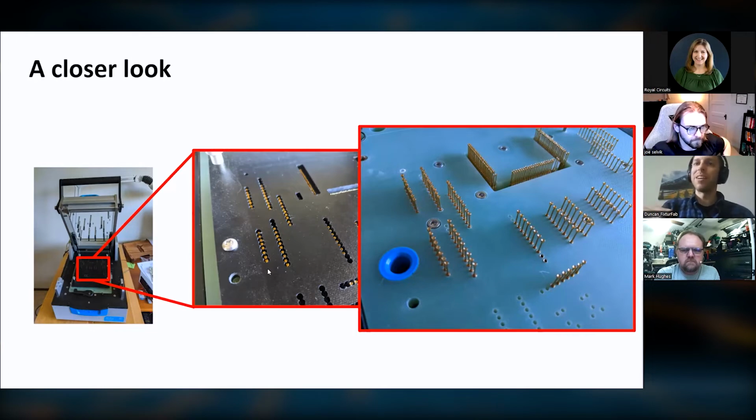One of the gotchas that people run into all the time when they first start building test systems is they won't switch off power to the board. And so sometimes, depending on what pin makes contact first, you can actually dump a lot of power through an IC or something like that, which can cause parts to blow up. And it's all just because you didn't turn power off and on at the right time. Whoops. So, yep. Expensive mistakes. So how do you deal with that?